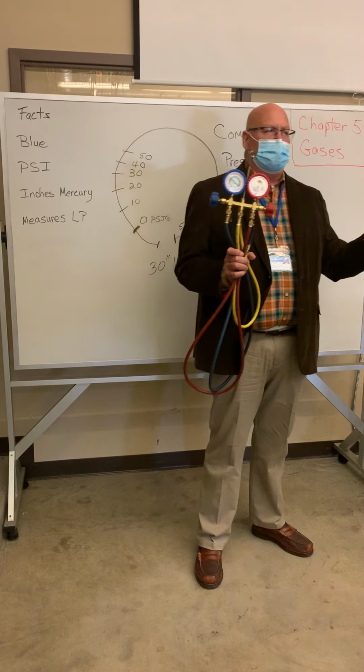On the high pressure side, we're not absorbing heat, we're shedding heat. We're getting rid of heat. We're doing this because we know that certain refrigerants, at different pressures, are going to be better at absorbing and releasing that heat.